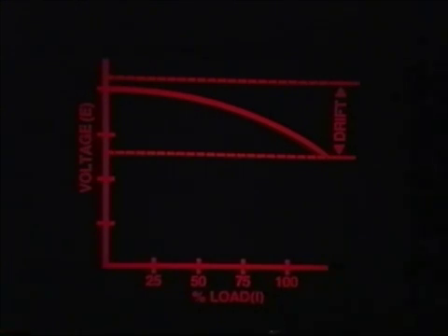The increased resistance from no current flow or no load to rated current flow or full load will cause the output voltage of the winding to drop gradually as the windings warm up to operating temperature. This drop in output voltage is referred to as temperature drift or just drift. This drift can have a substantial effect upon voltage regulation of alternators which are not equipped with an automatic voltage regulator or some form of temperature compensation circuitry.